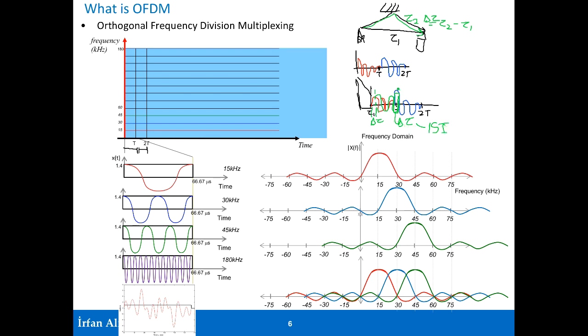In order to not have this intersymbol interference, where your previous symbol clobbers the beginning of your next symbol, the most intuitive thing you would do is, instead of starting your next symbol exactly after the first symbol is over, provide an additional delta time between them to take into account the worst case delay difference.